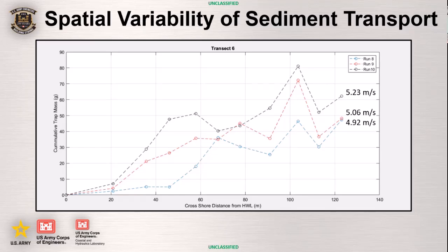If we are butting up against the high water line, then we're just outside of a moisture constraint for transport. And if we're ahead of the dune toe, then we're not getting into the flow compression that might happen as you get closer to the stoss slope. So really we're just trying to bound that subaerial portion of the beach.